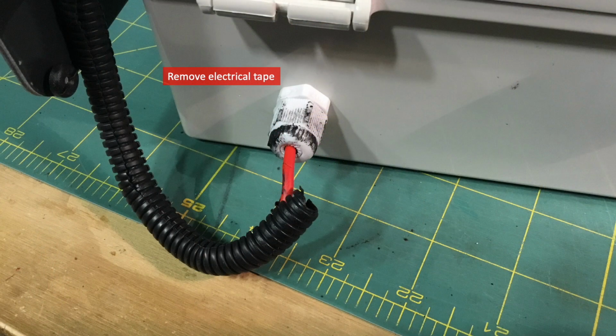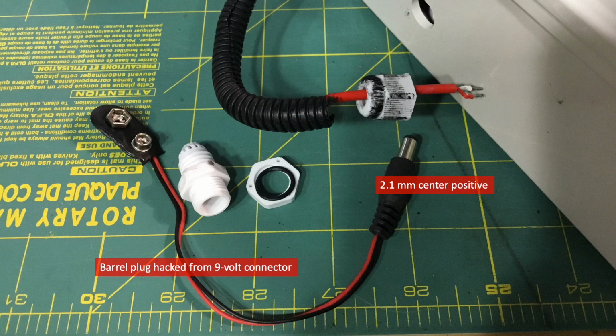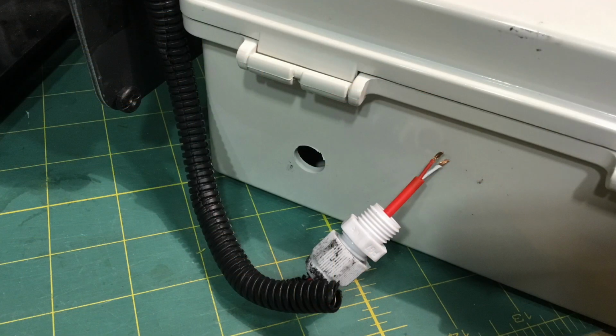To address this modification, remove any electrical tape holding together the wraparound conduit and cable where it comes into the box, and then loosen that fitting so that you can remove the associated cable. And here's that 9-volt connector with the 2.1mm jack I mentioned. You can cut off the 9-volt part of this assembly and strip the wires bare. And also take a few seconds to strip the leads off the solar panel cables so you have some fresh wire to work with.